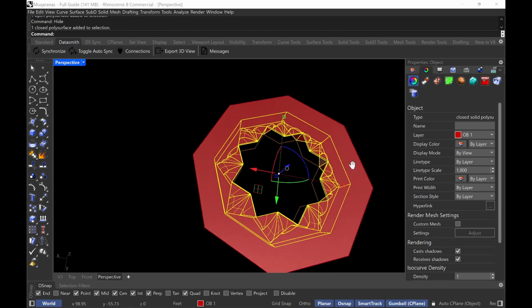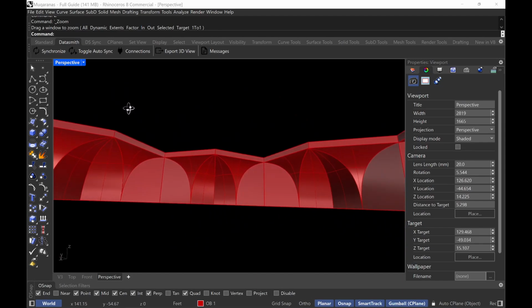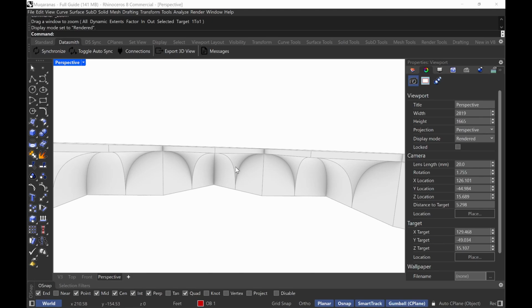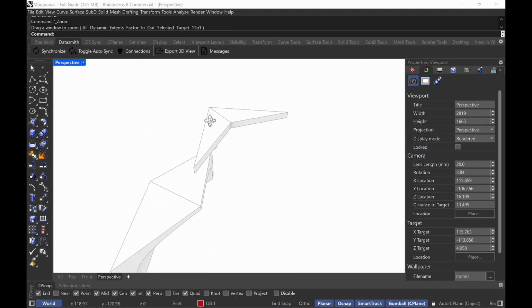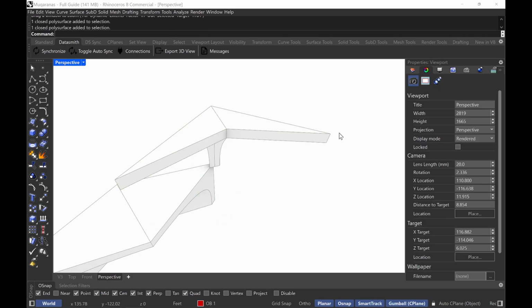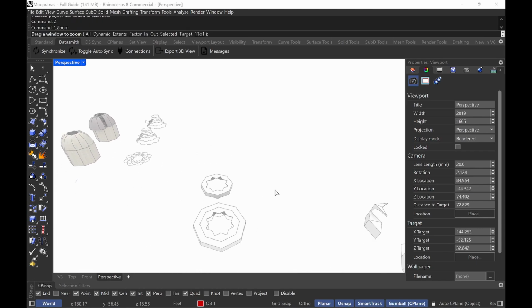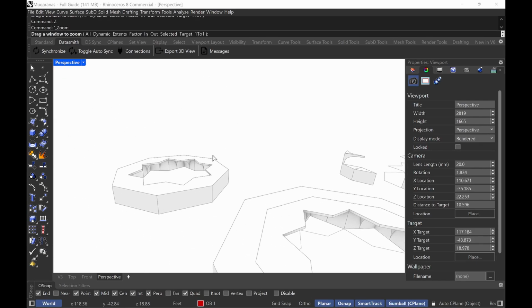You see, let me just go over here. Duplicate this. You see? So instead, you could technically model this individually and then mirror the solid. So if I go here, for example, I could technically model this, right, and just start flipping and mirroring each one individually. That's a method. Or you can just model each one out as a flat surface, and then once you're actually done with everything, you can go ahead and cut it all at once, or Boolean difference it all at once by stacking it into modules, right?